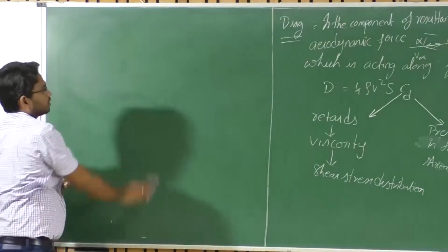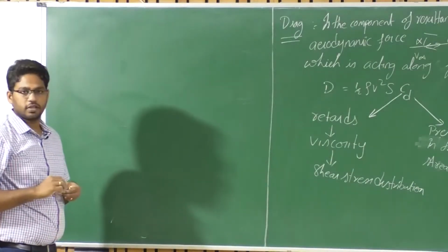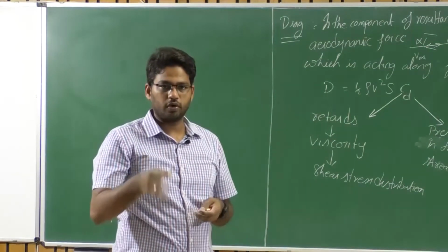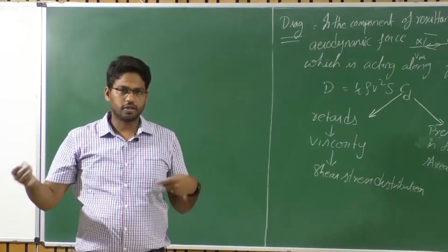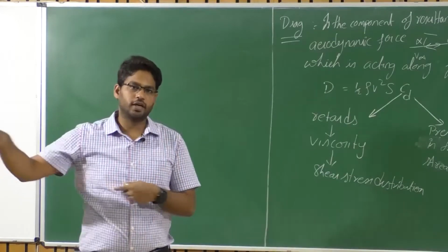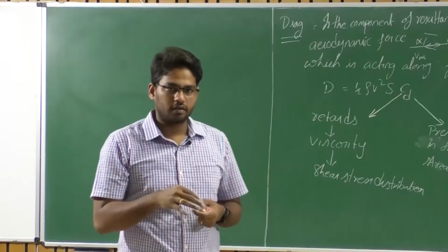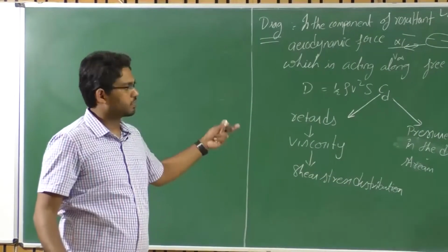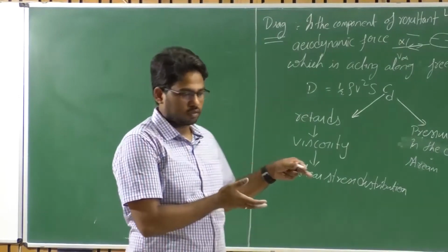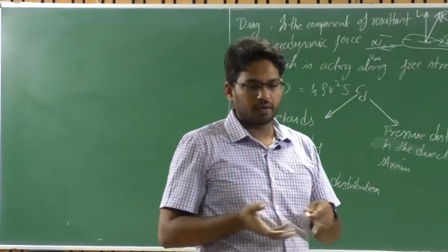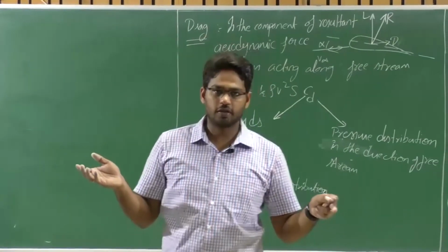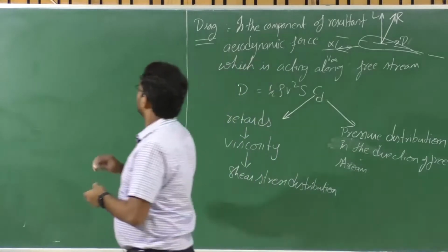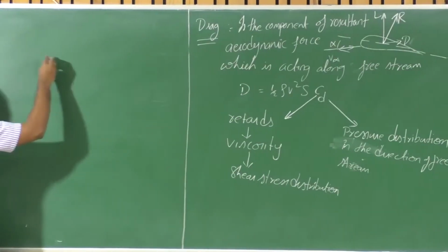Do you remember? We talked about lifting line theory, where there is a horseshoe vortex with a bound vortex and two associated trailing vortices closed by a starting vortex. It characterized high aspect ratio wings in terms of their lift curve slope. So we can use that theory to characterize high aspect ratio wings. Am I correct or not? While deriving the theory, we also witnessed that there is an induced angle of attack, isn't it?